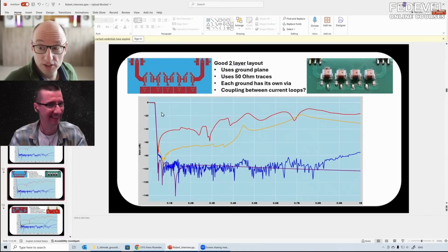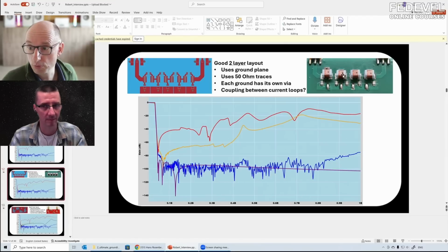Now, a number of things are going on. This took me a few hours to figure out. It turns out there are two things. These are air inductors, so their fields run like this around them, and they are so close together that they're talking to each other. This inductor, which is supposed to not communicate at all with this one, is actually working like a lousy transformer.